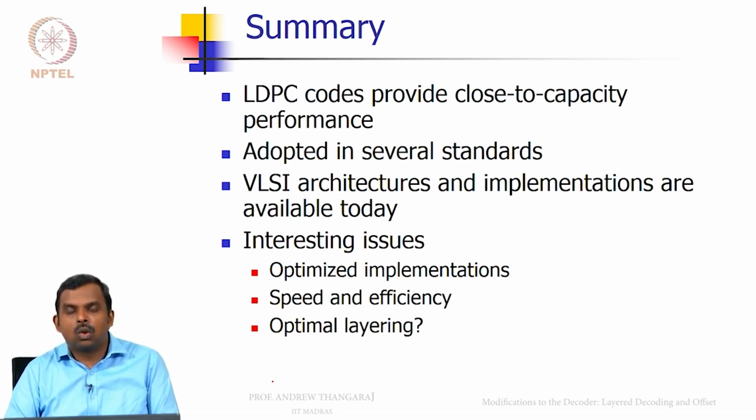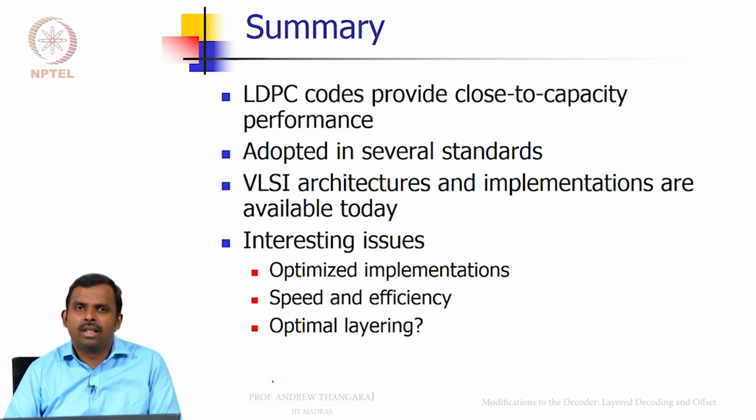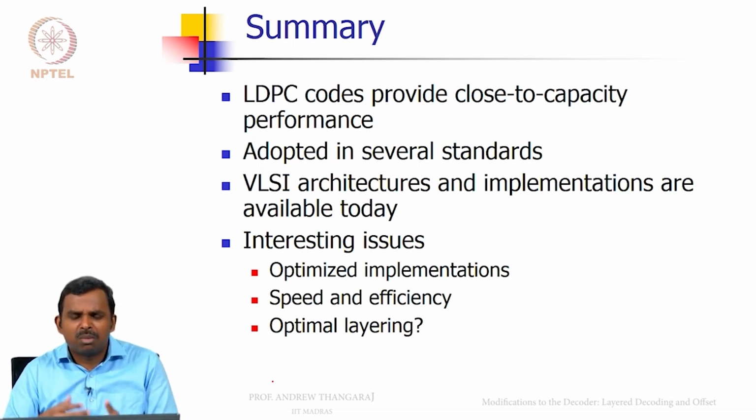So in this course, at least, we'll focus on implementation. In particular, we will try and do a MATLAB implementation for the layered decoder. We'll take one of the parity check matrices in the 5G standard and build a layered decoder for it. Just the storage matrices and then the received value simulated, let it go through the layered decoder, do the subtract, row process and update. Hopefully you agree with me, the operations themselves are quite simple. It's just a question of organizing the memory and moving things around.